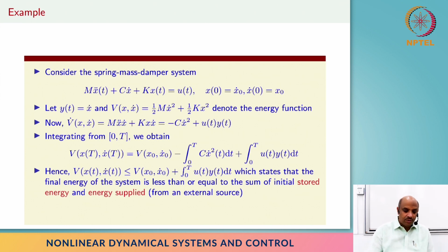So when we don't have inputs, the inspiration for Lyapunov stability was to find a Lyapunov function which acts like an energy function. If that is bounded, then the system is going to be bounded, and if that decreases throughout time, we end up with an asymptotically stable system, especially if V happens to go to 0, right?